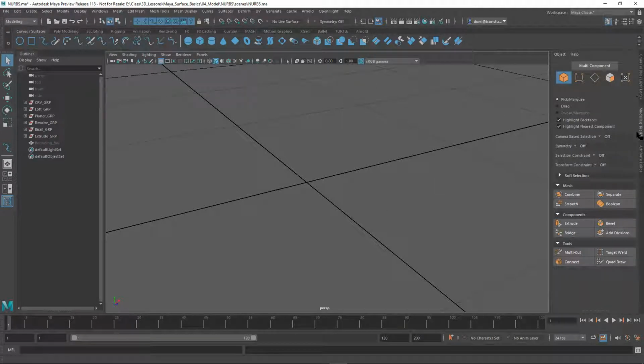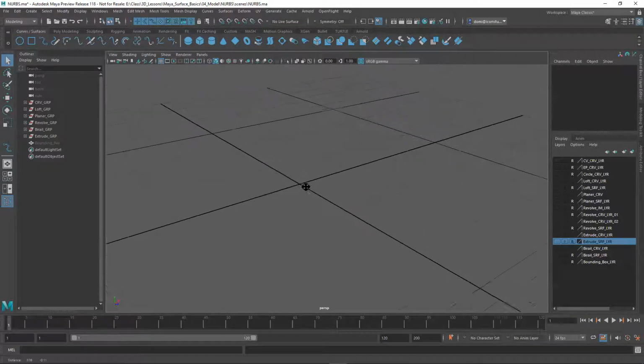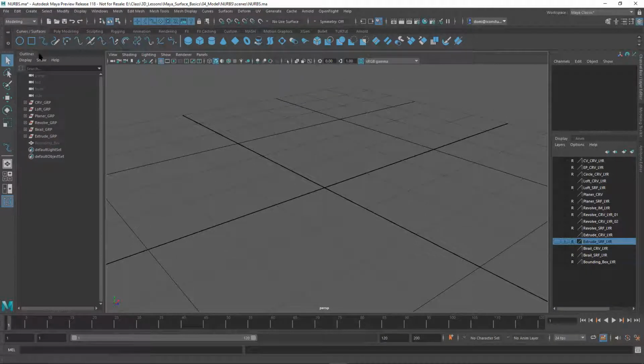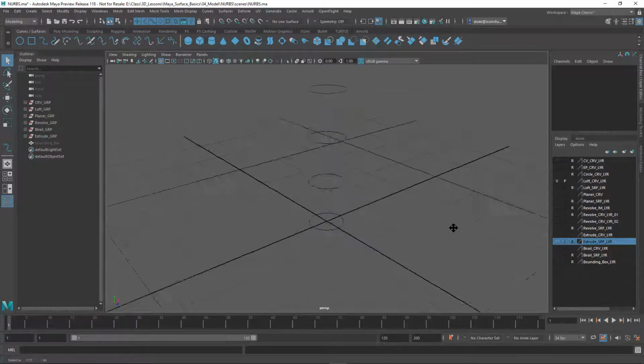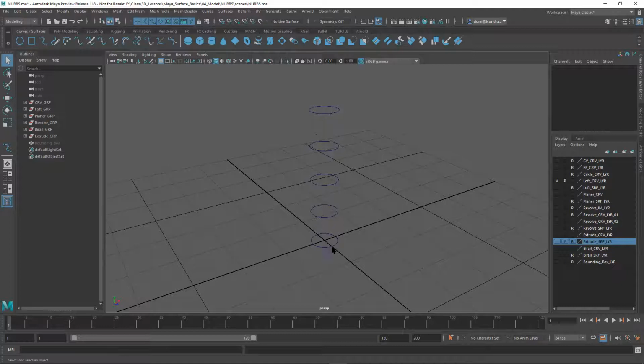Okay, I'll get back here, and I'm going to show you the different tools to create these surfaces with. Again, like I said, it's going to be based on curves, and these are some of the curves we've gone over here. I'm going to show you this first set. I've already created these, so we don't have to spend time creating a whole bunch of Nurbs. I want to show the actual tools. So what I did was I created a circle with this tool here. And then you can either duplicate it and copy it up, or you can create an array. You can go duplicate special and give it a distance. There's a lesson on that, so if you want to figure out how to do that, you can go over that lesson.